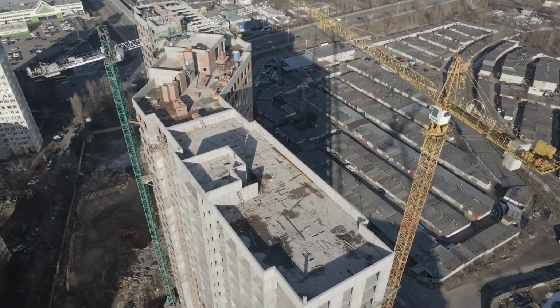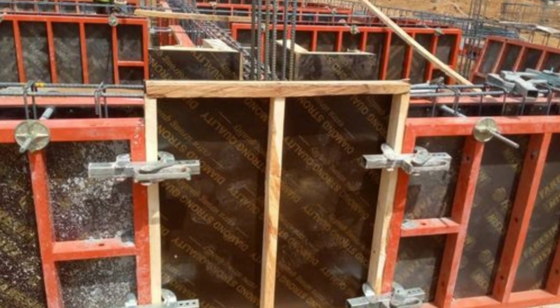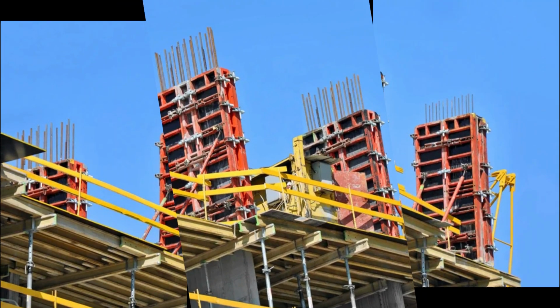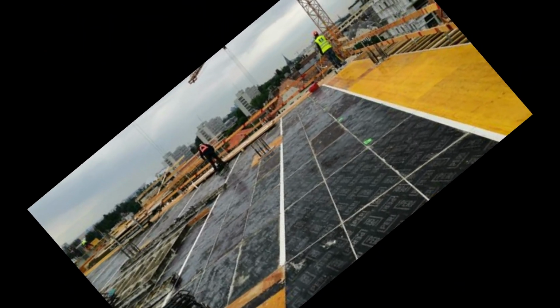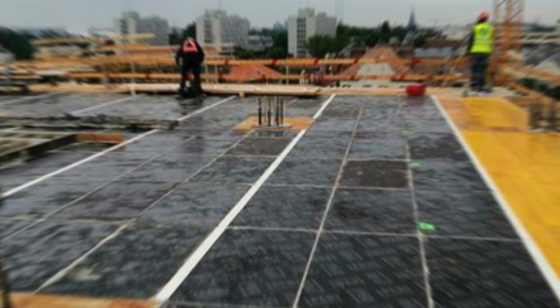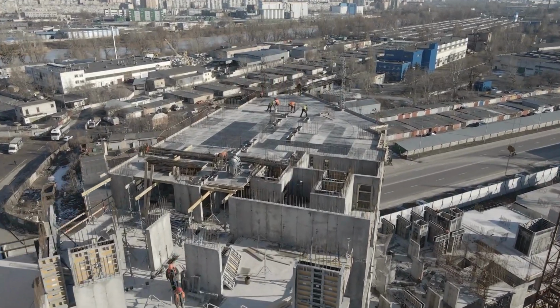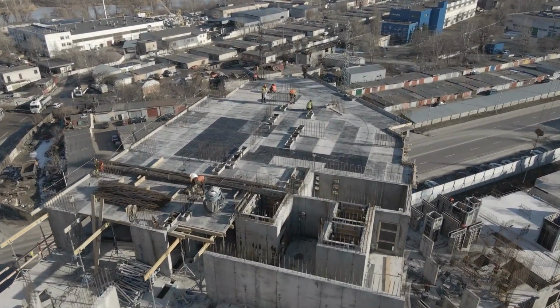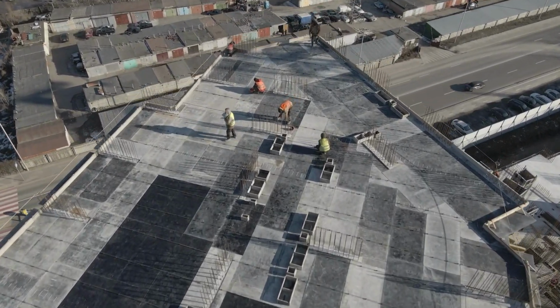The formwork material must be available locally, cheap, and can be used more than one time. Try to keep it as lightweight as possible to prevent extra load on supports, especially in horizontal shuttering. Lightweight formwork also can help to reduce labor costs or efforts. It must be fixed in line and levels as per the drawing. Formwork material should not be damaged or rusted, which affects the quality of concrete finishing.